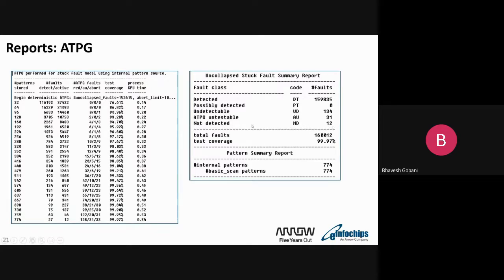So what can we do? We can identify a certain region, and based on the region we can do analysis, and based on the analysis we can put some test points in order to get more controllability and observability. Once we insert some flops or test points, we can get the output of a very internal node to those flops, and we can detect those faults.